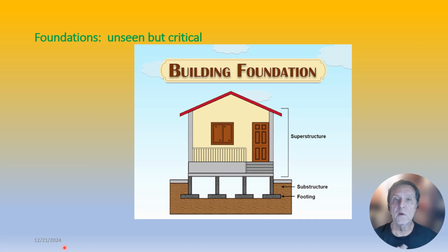Okay, so in a simple case for a house, you can see that we found the house on shallow footings onto stable material, whether this is bedrock or compacted soil with high density and strength characteristics. You have to have your footings on good, strong, stable, durable material which won't settle or swell or be subject to saturation and weakening by groundwater and the like.